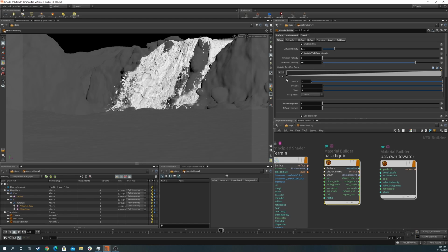The interesting thing is, even if I set it to 0, we still have some values after we added the intensity. That is because the ramp, if you see on the very left, the default value is 0.1. However, I don't want to see any of the color introduced to the shader if there's no vorticity. So I'm gonna set the value to 0.